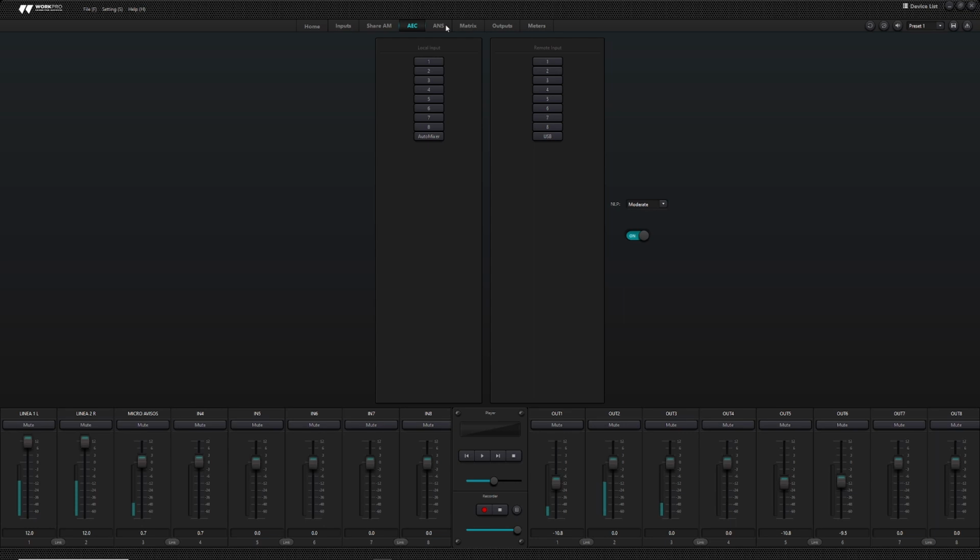The ANS automatic noise suppression mode operates similarly to the AEC mode. We activate it and see that in the drop-down level it gives us the options to act on 6, 12, 18, 24 and 30 dBs. We select the channels on which we want it to act, including the AUTOMIXER, the USB player, and the AEC module.